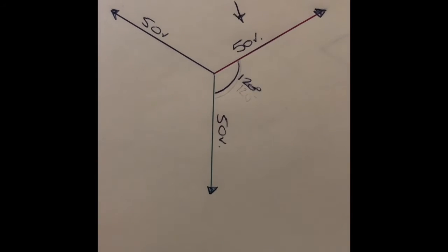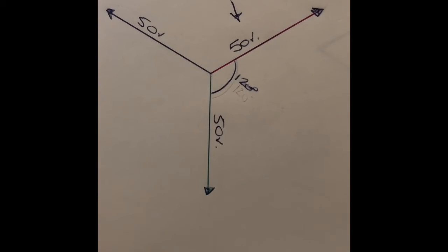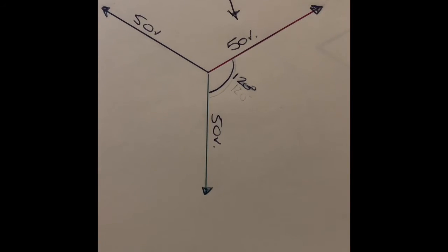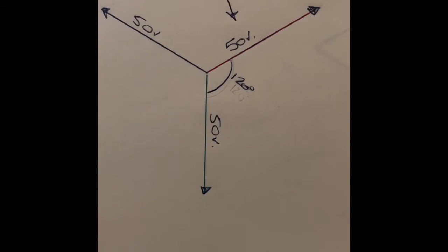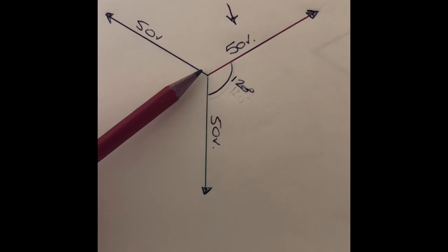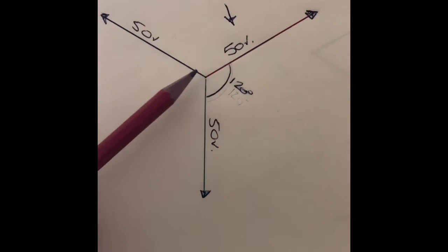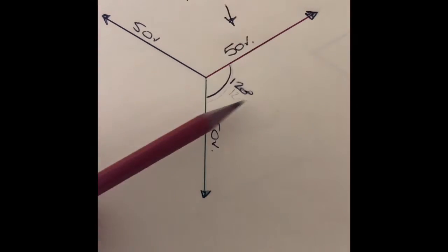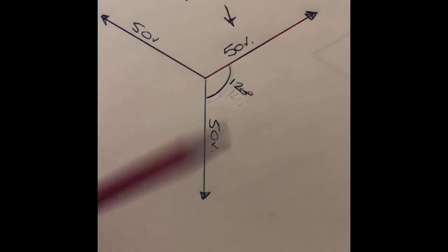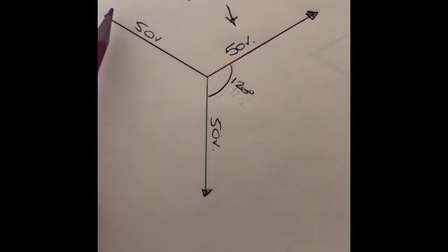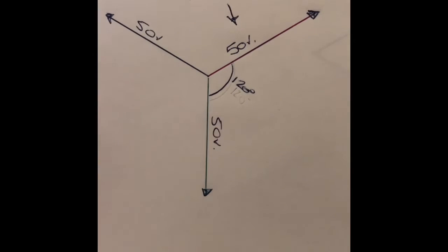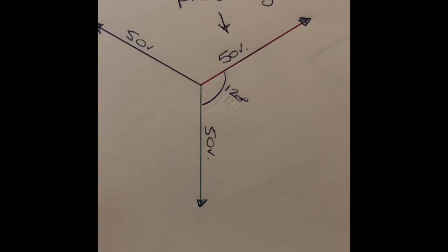This is a star network. This is what is now installed right across the UK from substations out to all of their commercial or residential situations, because from this point here, they will basically earth their star point, and then we can take single phase to neutral, or we can take two phases, giving us 400 volts, or we could take all three phases for our three-phase induction motors.